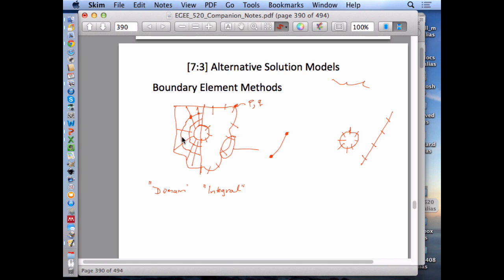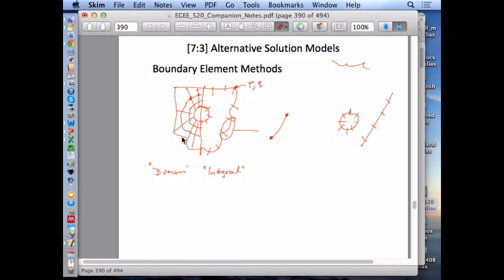So we will talk about boundary element methods. You can equally apply boundary element methods to all of the problems that we've solved. So we've solved problems for flow, which are very straightforward. You can use them for transport problems. You can use them for solid mechanics problems. But because these have just 1 degree of freedom and it gets kind of complicated, we'll look at them only for flow problems, not transport problems at all. So we'll talk about the rationale of how they work today for flow problems.